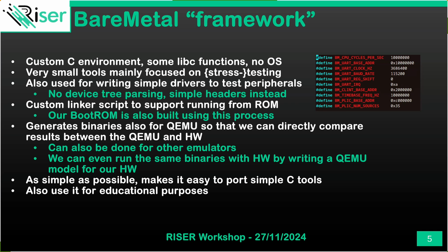These tests need to be very small, on the order of a few kilobytes. For example, when you don't have DRAM and you may have some SRAM, you may not even have SRAM. There is a chance that all you have is your level 2 cache that you can use as scratch memory. So those tests need to be very, very efficiently written.